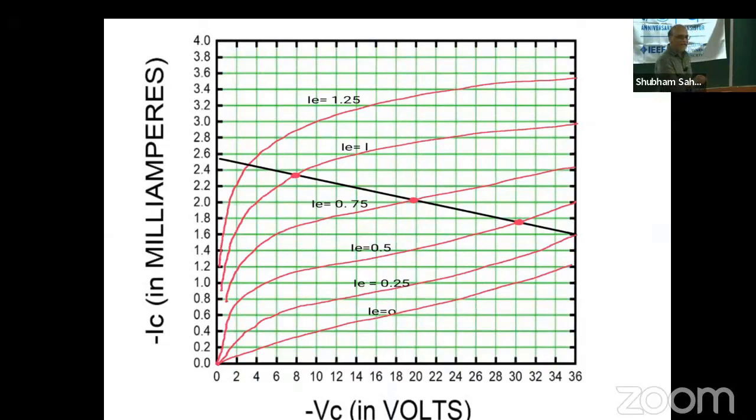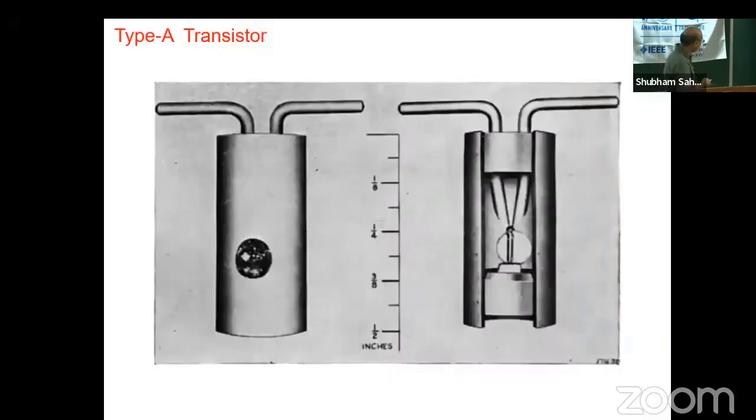So these are the characteristics of the first transistor that you can see here, right? And it was operated in common base format. So these characteristics are given for different emitter currents here. Okay, and this was the load line. This was where it was biased, and this is what yielded the amplification that I just talked about.